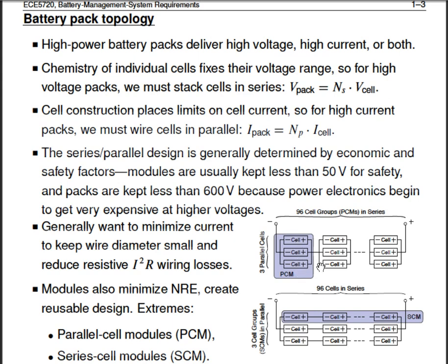Suppose the second group has a net voltage of y. That means at least one battery source has the maximum voltage y, and this y is connected plus-minus to x. So when we combine the series combination of these parallel sources, the net voltage will be x plus y.